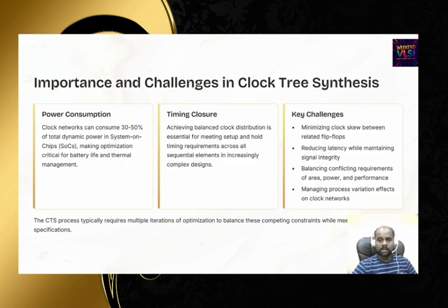The other one is OCV, on-chip variation. This depends upon the divergence of the clock tree. For example, when two flops are talking to each other, if they are sitting together and connected to the same buffer, the divergence is very small. But if they are far apart because of your placement, then you will see buffer trees that are uncommon to both these flops. This will create more OCV effect.